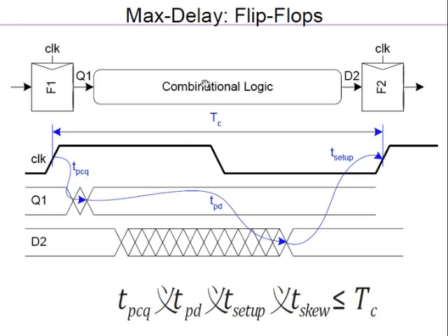We know that in a synchronous design you have pipe stages. Here we focus on a pipe stage where you have flip-flops at the beginning and the end. For example, this could be a 64-bit adder with two 64-bit inputs and one 65-bit output, so there are a number of flops here.